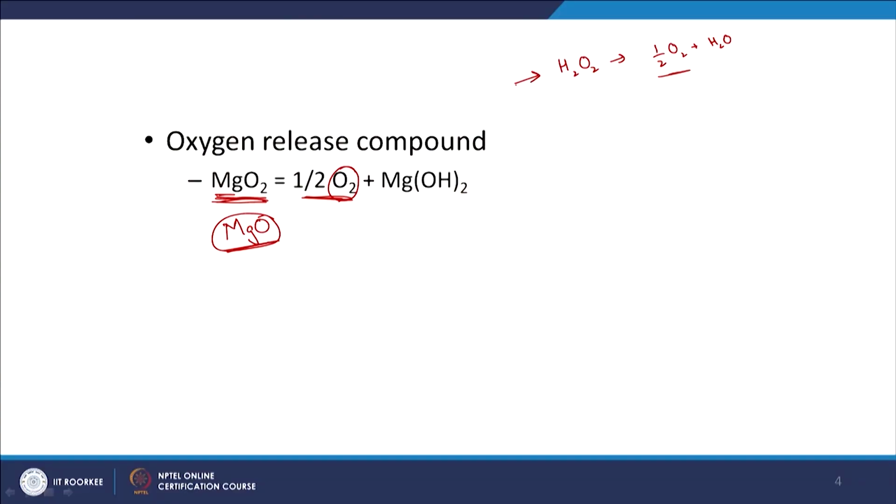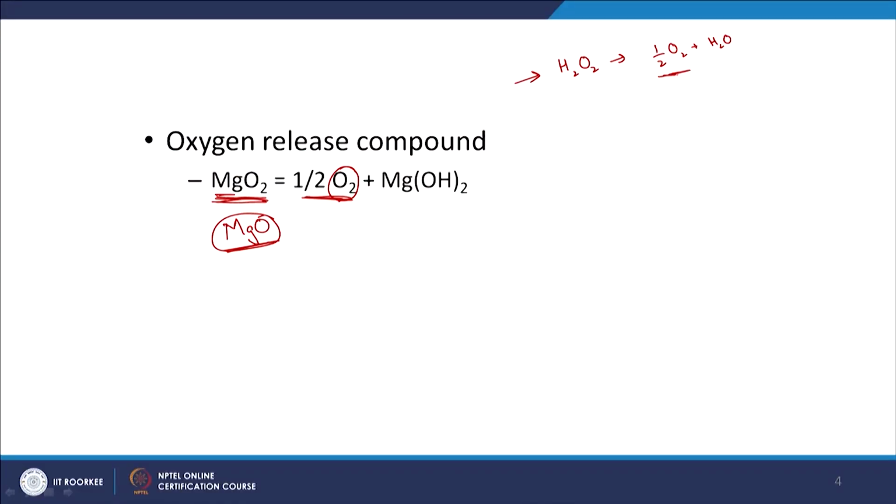So one aspect to keep in mind is that sometimes, while taking a syringe or as an antiseptic, hydrogen peroxide is also used. So what does that mean? It is an antiseptic, right, it is going to inhibit or kill the relevant microbes. So obviously you should not add hydrogen peroxide at very high concentrations, because then it is going to be toxic to the microbes. So when you are adding compounds like hydrogen peroxide, which are strong oxidants, or even other compounds, you need to be careful that you are not introducing compounds that are toxic to the microbes, right. As in, if you want higher oxygen concentrations, you should not just dump a lot of hydrogen peroxide. Why is that? Because it is going to be toxic to the microbes, right. So there are such different aspects.